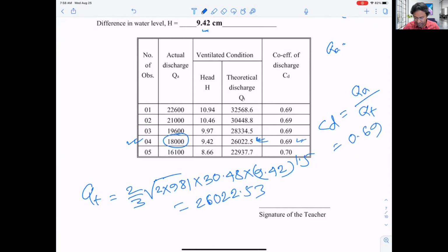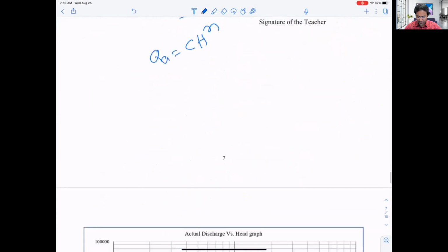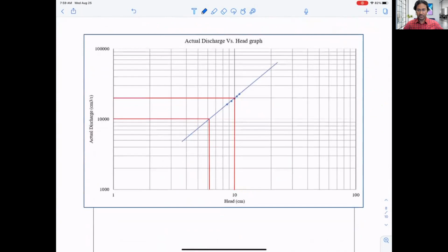So we are filling up this table for different flow conditions and for different groups. So now what we have to do is plot this value with that value, and we have to calculate, right, because we derived that equation, C is to the power n. Let me show you that. I already plotted, so I'll show you how to plot this in Excel using that value. And here is the line, so we can read, right?